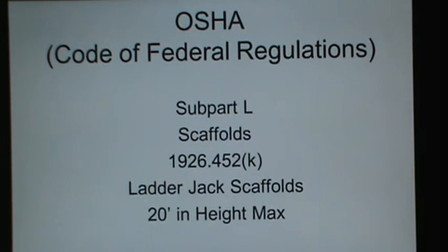We'll jump over to 452K. 452K is in bold print. It says ladder jack scaffolds. Platforms shall not exceed a height of 20 feet on a ladder jack. Make sure you can find that.